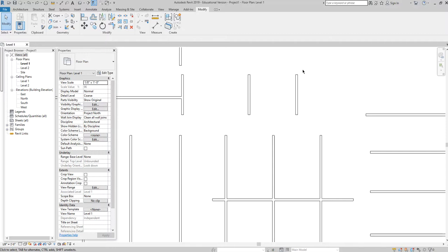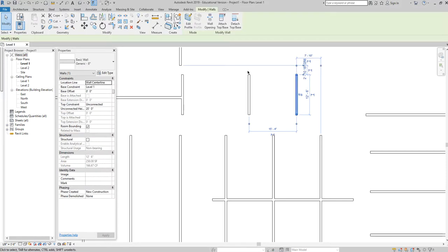And in Revit, you don't do that, right? You don't use enter to set a command. And so when I initiate the command and then select, I want to hit enter, and it doesn't work that way. So I think my workflow of selecting an object or objects, then executing the command works a little bit better, okay?